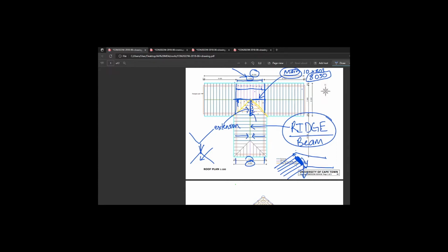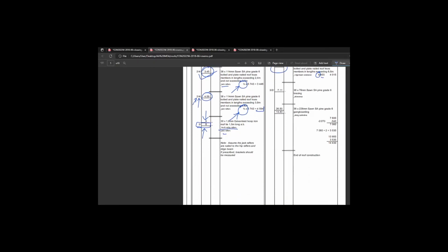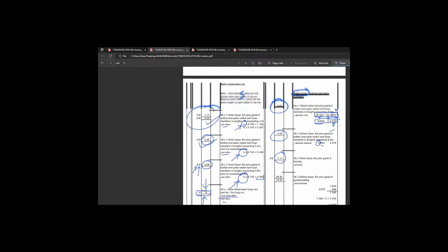You must go one step further to fix the whole system to the rest of the roof, so that it is actually supported and makes sense. Okay. And I think it's important to make sense of measurements, because it makes it easier. It definitely makes it easier. What did we say here? We did the 8, we did the extension, which was 5. Okay. The bracing is exactly the same measurement as the hip rafter.